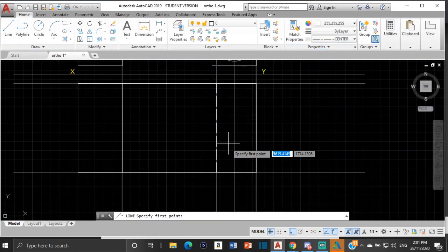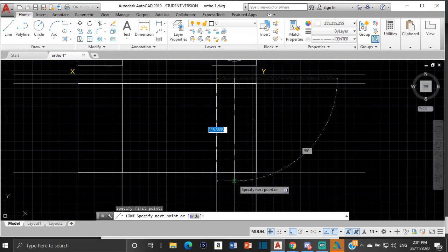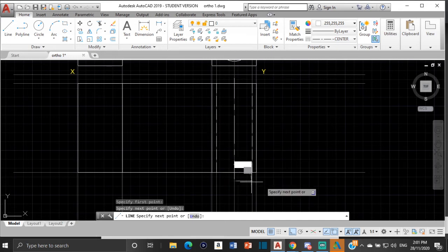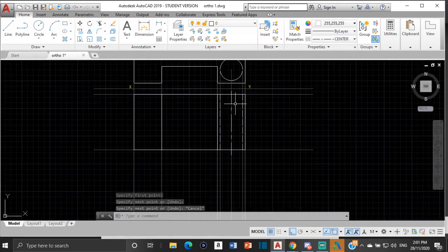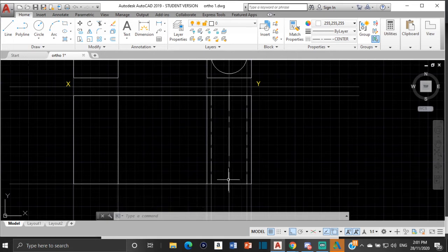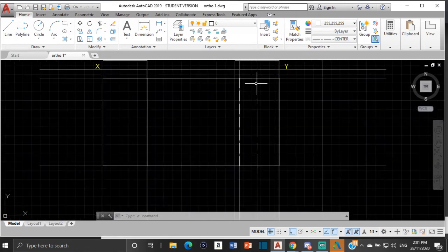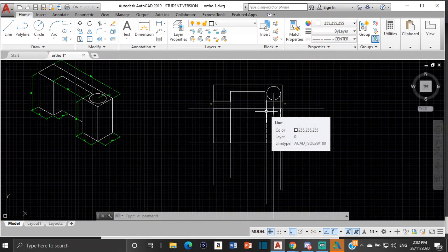So I'm going to draw the center line through the figure. I'm just going to start a little bit outside of the front view itself, and then draw that down a little bit outside of it down here. So the center line works like that. It doesn't really go exactly from the top here to down here. You start it a little bit outside and bring it down to represent it. So that's my center line. Nice. So what this says to me now is that this is a circle. This hole is a circular hole. So that's my front elevation.